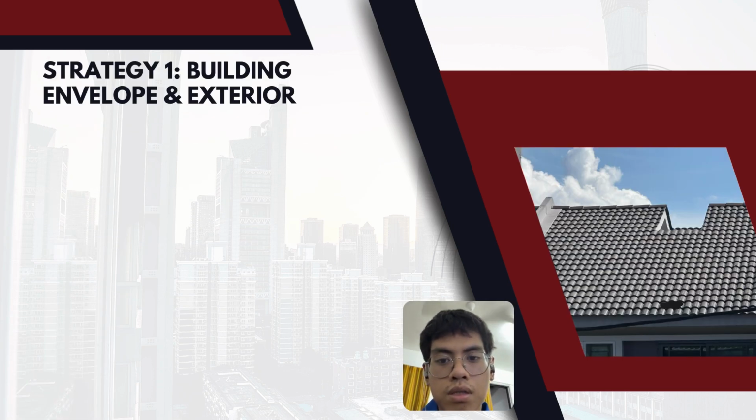For the first strategy, it encompasses the building envelope and exterior. So we have focused on two areas of the house. The first one is the roof, and the strategy to be done is preventive inspection and minor repairs. The procedure starts with visually inspecting the roof surface, ridge caps, flashing and fasteners, and also replacing cracked tiles or tightening any loose sheets. The frequency is every 6 months and after heavy storms.